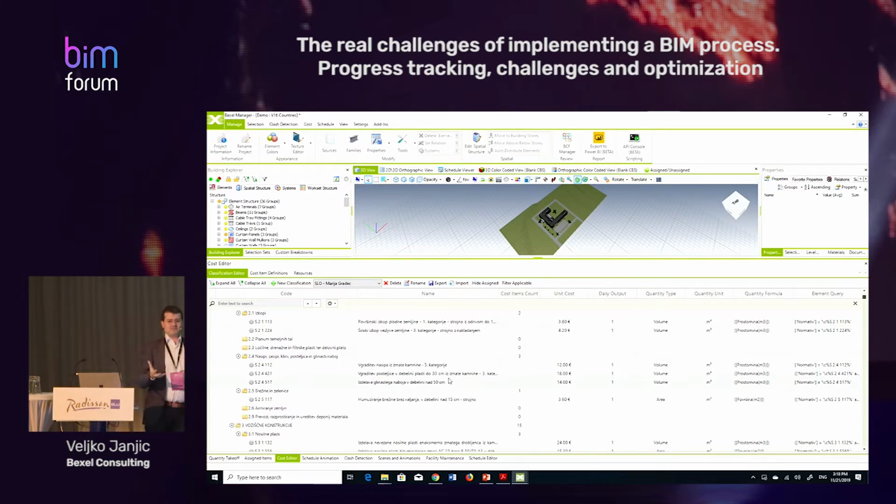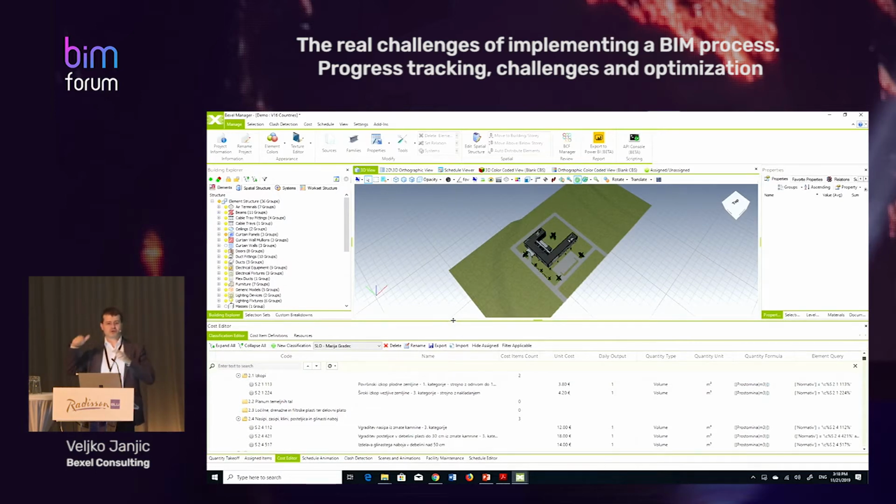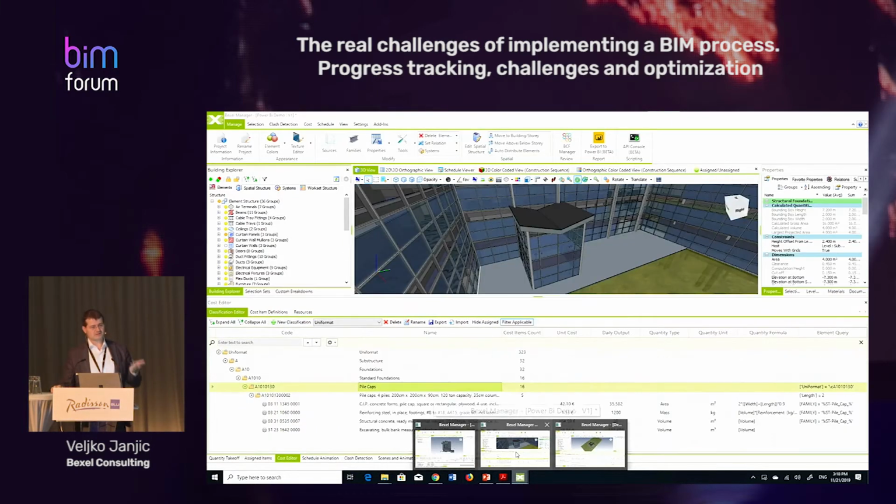So then the system automatically, when the designers in that infrastructure project used 7 BIM authoring tools, completely different softwares, but everybody add new property, which is called normative, and add code. And then the system automatically did the match. For example, I think we have add-in for Revit, where you can choose from the list type of the codes which are automatically matched with Bexel Manager cost database. So this is the way how you can customize your classification. So you see classifications customized, cost items classified.